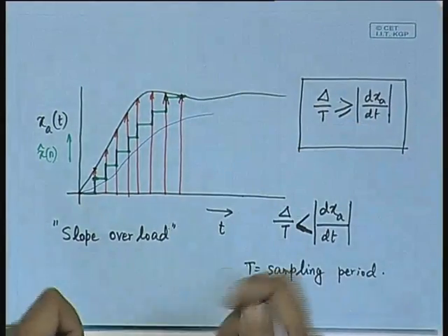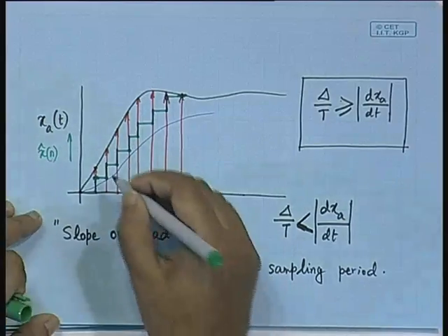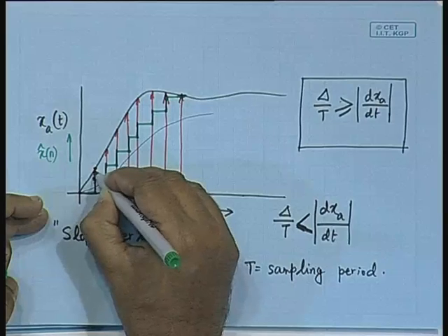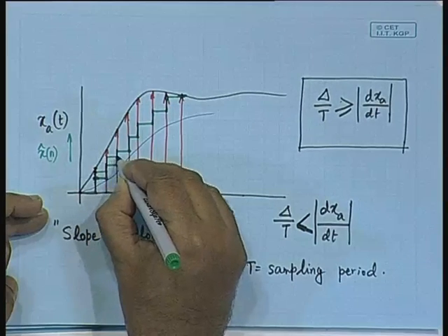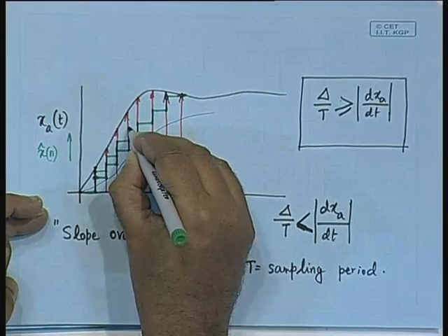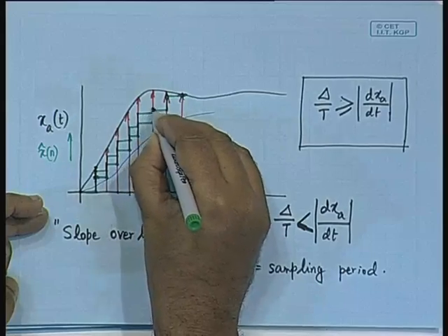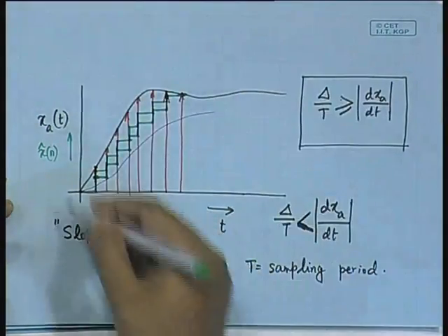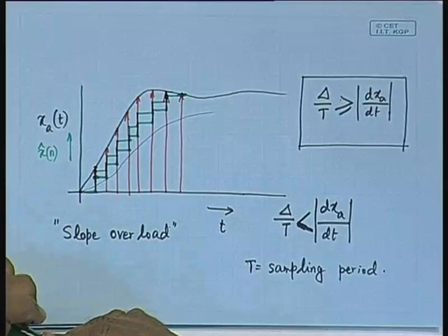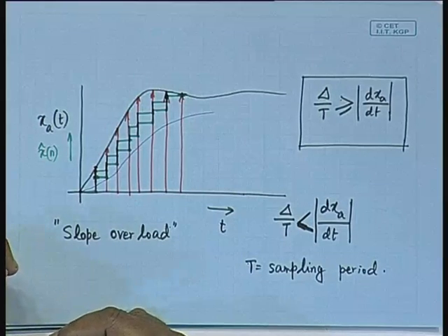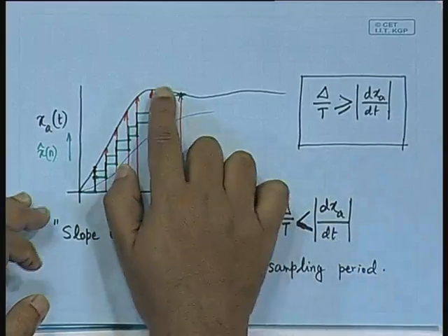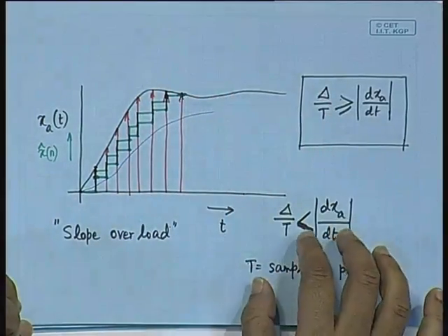Had it been an increased value of delta, then we would have been definitely better off, because in that case our encoded waveform would have stepped higher than this. So, we could have obtained something like this. If we increase delta even further, we could have tracked down the waveform. That would not have been any difficulty. But look at the uniform part of the waveform now.